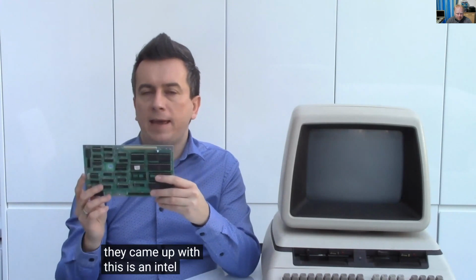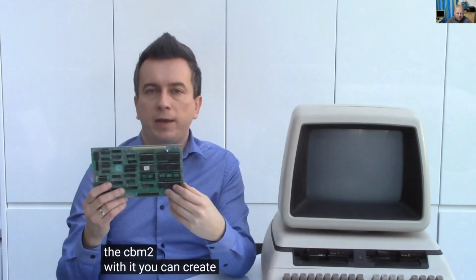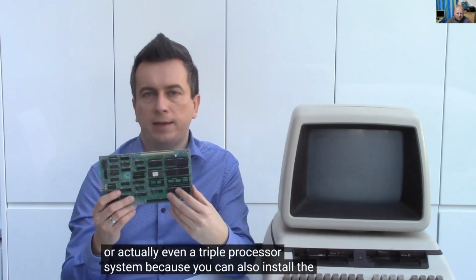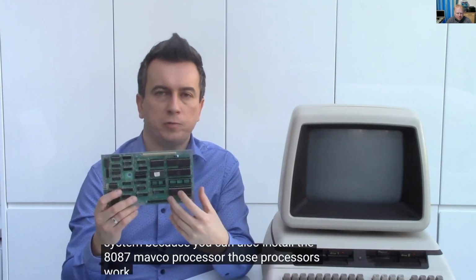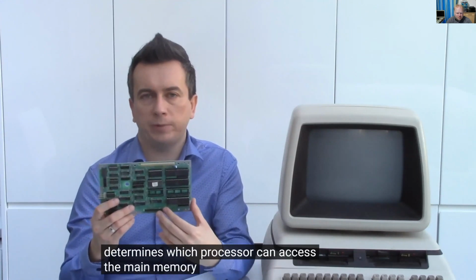This is an Intel 8088 processor card for the cbm-II. With it, you can create a dual processor system, or actually even a triple processor system, because you can also install the 8087 math coprocessor. And those processors work together. There is an arbitration mechanism which determines which processor can access the main memory.